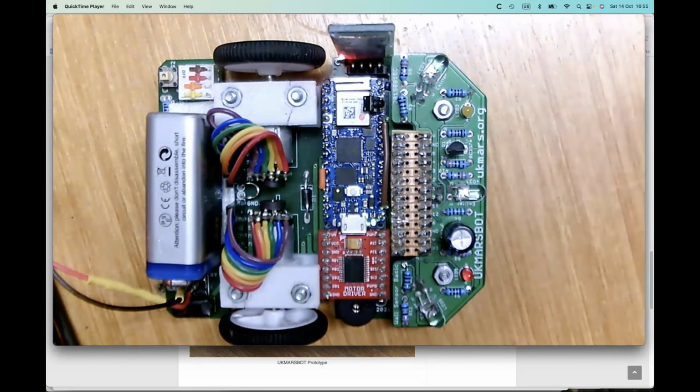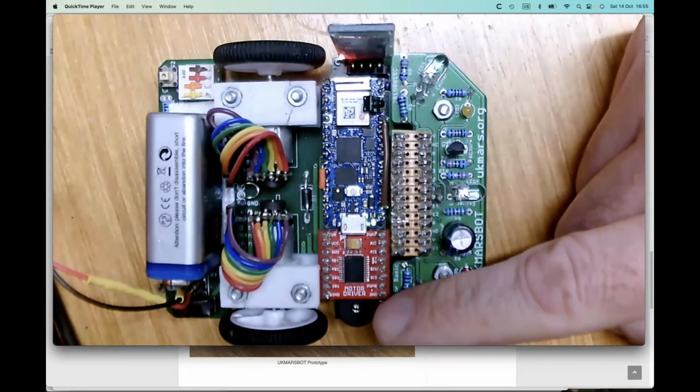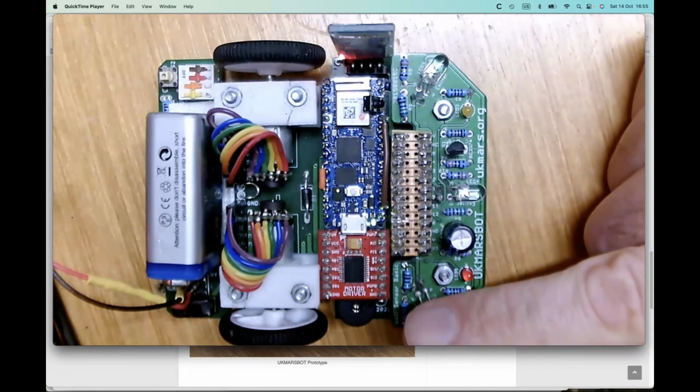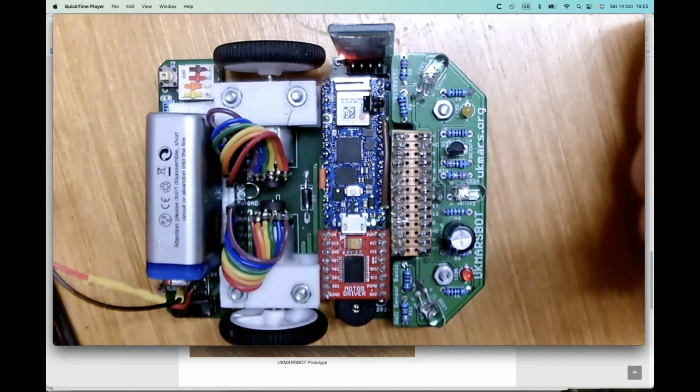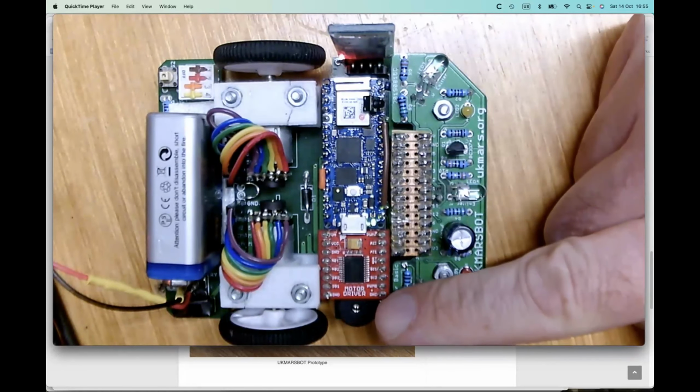It's tricky when these robots move more than slowly. It's tricky to know what they're going to do. So you can obviously log data, and you can have commands to get it to do particular things, particular Forth commands. But having a bit of audio feedback, just a beep, I find quite useful. You can perhaps more easily see when it's going to start a turn, for instance. So originally I had, instead of the LED, I put a self-oscillating buzzer on this.